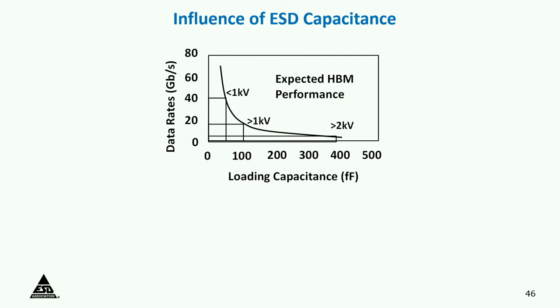That's why I need to show you the slides about the space that is available to share between ESD and RF performance. There are a lot of techniques that are involved with putting inductors into the circuits so that they're transparent to RF but can mitigate some ESD. There are a lot of circuit techniques, a lot of classes that are offered on RF design for ESD. So that's a completely evolving field that is coming on. RF is very, very sensitive to ESD. In fact, RF designers don't want an ESD device, nothing.